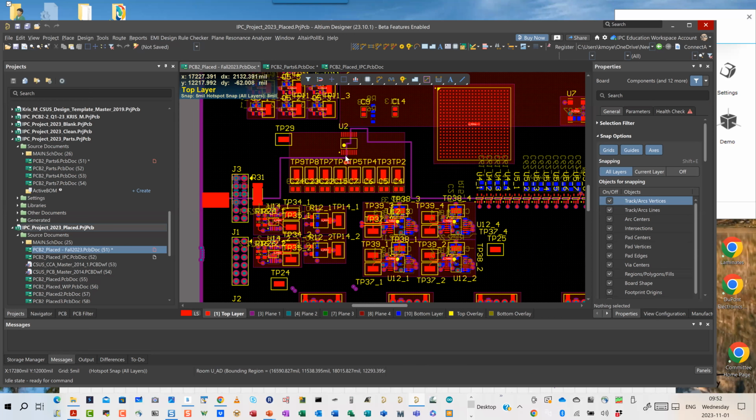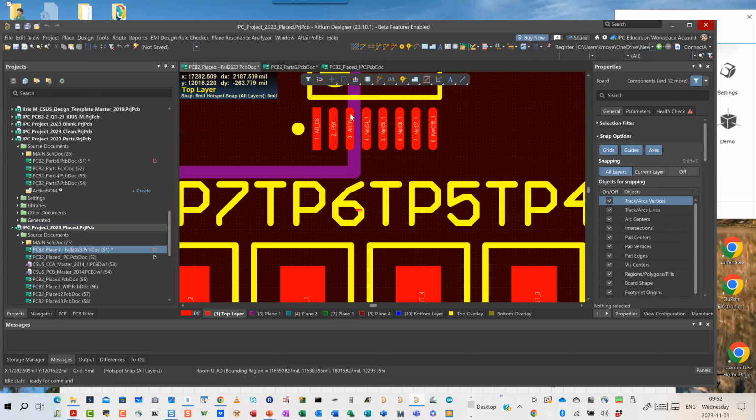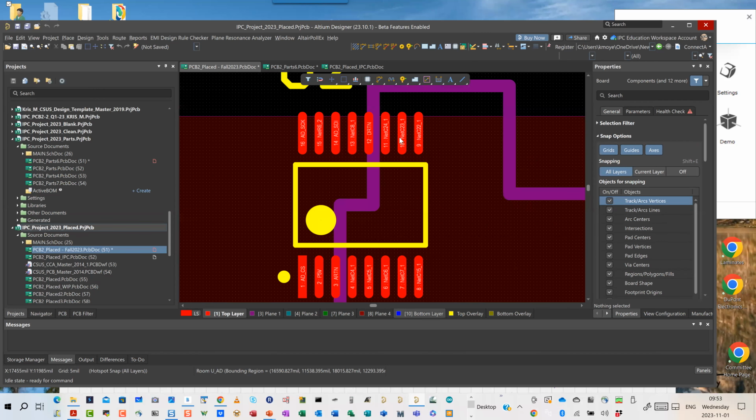So it's an oddball way if I'm trying to straddle an analog to digital boundary right here. So I had to move the split plane boundary so that the analog return, and actually I should try to move this over a little bit and then kick a little bit there. But here's 5 volts, here's the chip select, so that's digital. These are all the analog inputs right there coming from our A to D circuit along with those there.